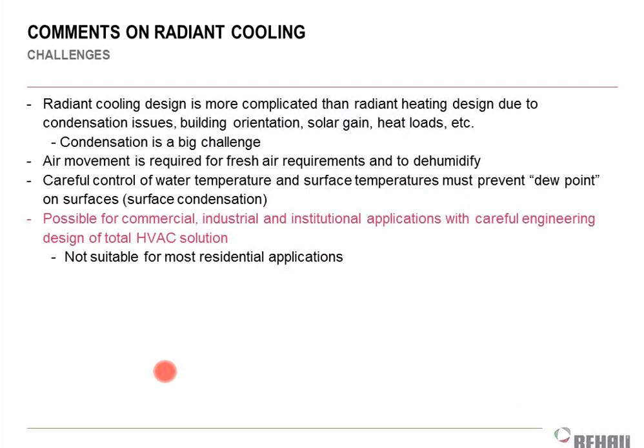The main reason is with radiant cooling, I don't have any way to dehumidify the space, so I need to have something else doing the latent control. If I just have radiant cooling, chilled water running through these pipes, it's going to cause a condensation issue on the surfaces, which is the floor, and people are going to get injured. So I have to have some way to dehumidify the air.